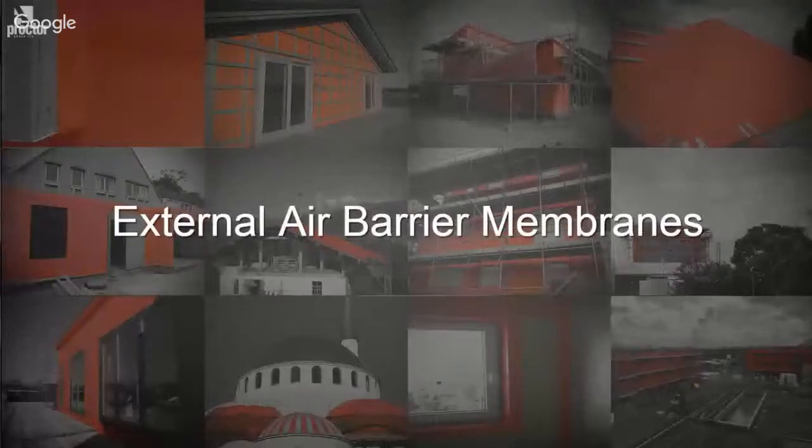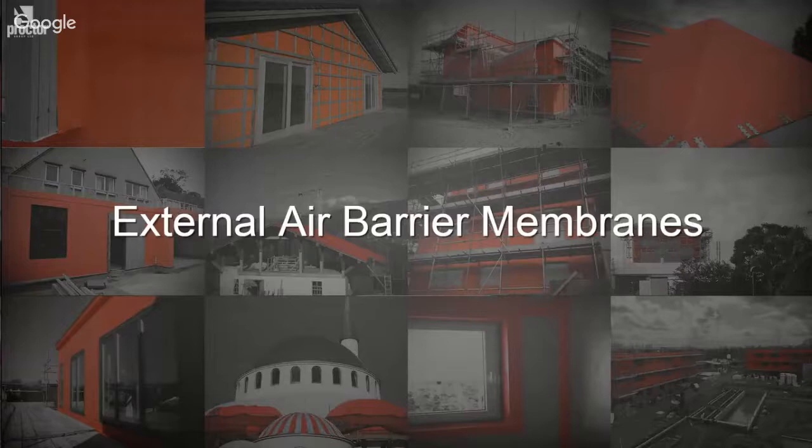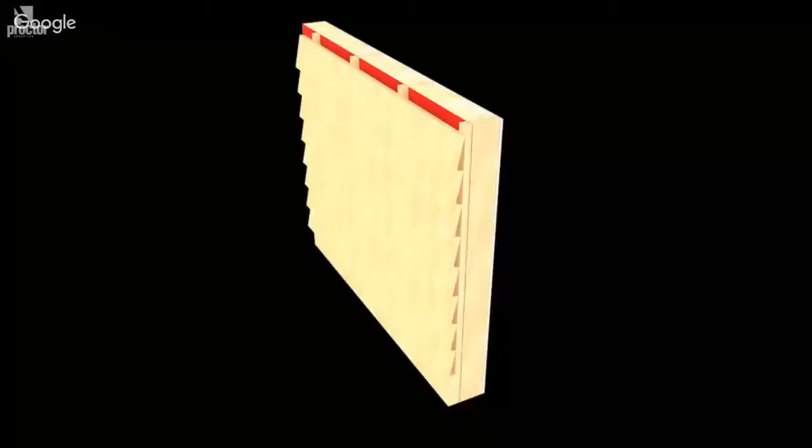One of the more recent construction membrane developments is the use of external air barrier membranes. Now, this represents quite a significant departure from the accepted traditional practice. However, having a membrane which is highly vapour permeable, but also acting as an external air barrier layer, seems to be quite a comprehensive way of achieving the building's airtightness strategy.